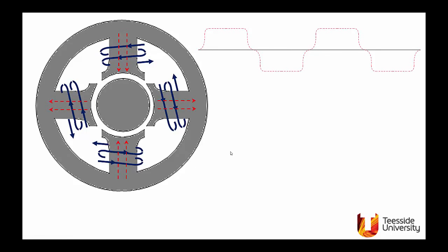A four-pole configuration is like what is shown. Again, the flux lines will enter and leave the iron perpendicular to the surface, and they go in a closed line. For example, this flux line will go something like that, and then here it will cross, and here it will cross radially, and here it will do something like that, and this one will go this way and this way.